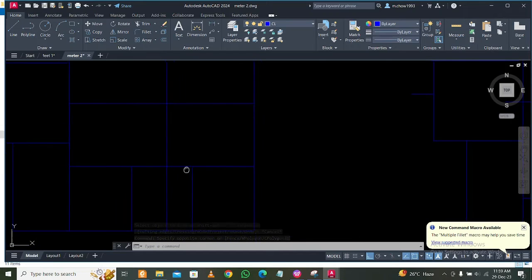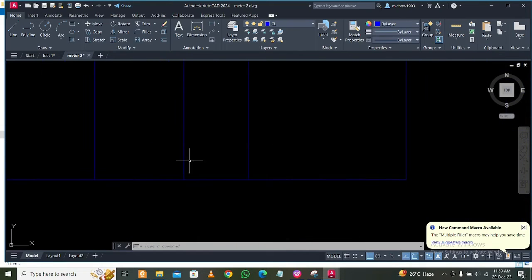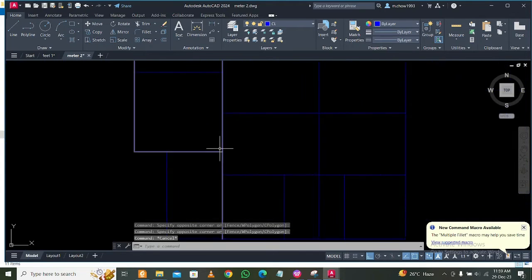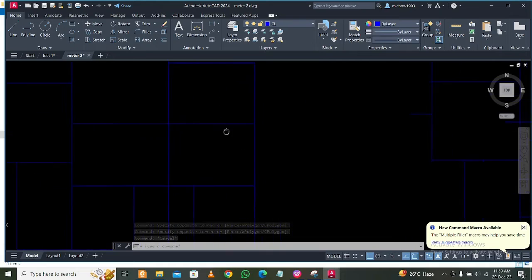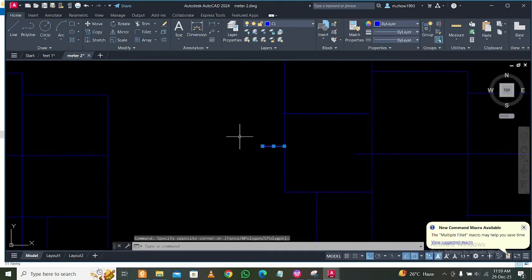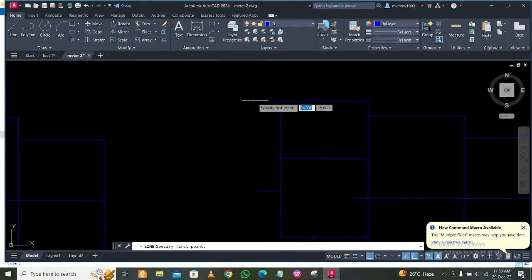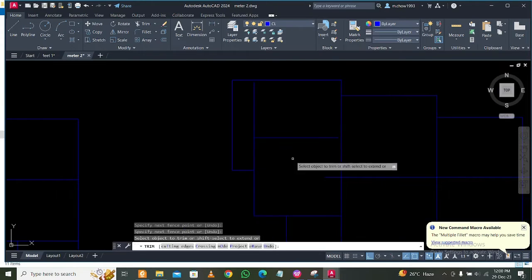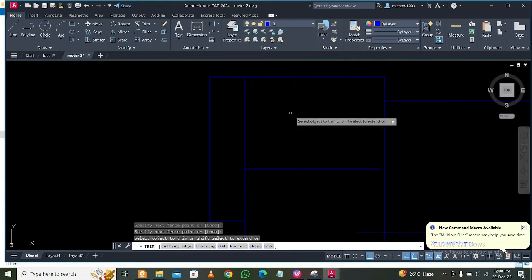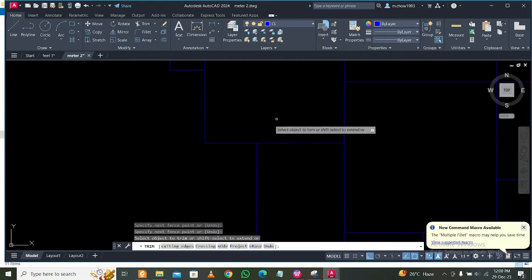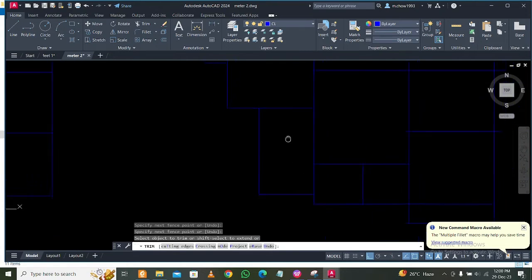So let me check and correct this. I'll not skip this part because this is important. Anyway, you have the proper file, but whenever you check, you have to check the process properly. So that's why I'm not skipping this part and keeping it here. Okay, yeah, this part you can give a beam here, trim this part, and shift trim this, so it will join here. Shift trim this, it will join this side. I think trim this part, and yeah, this is joined perfectly.